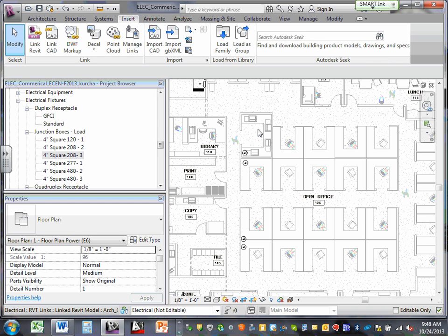Okay, done with loading these, gentlemen. Let's circuit them, but maybe drop before we circuit. Don't circuit before you drop. Why? Because when you drop them all, you can see where your receptacles are located. Then you start circuiting them based on 6 receptacles in one circuit. If you don't have them, you can't circuit them. So that's how you do your receptacles here.